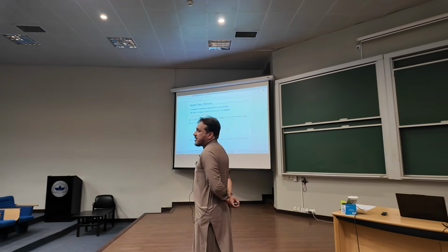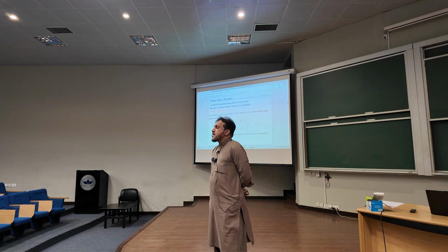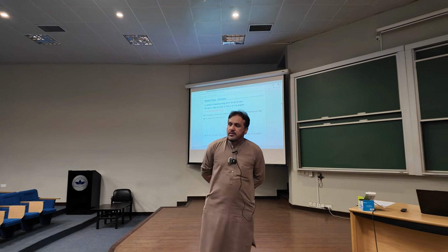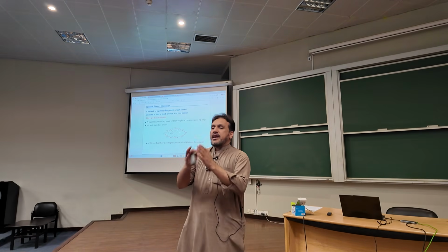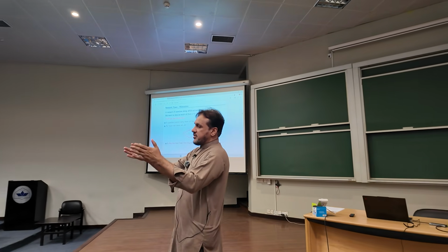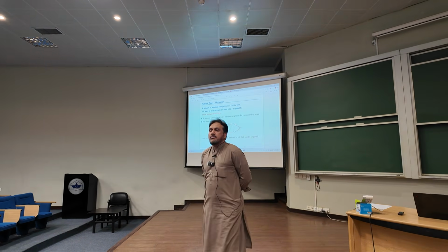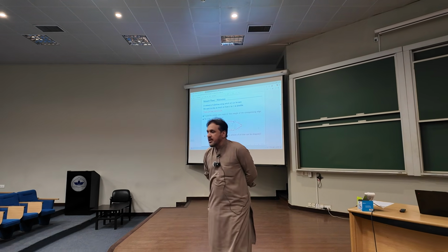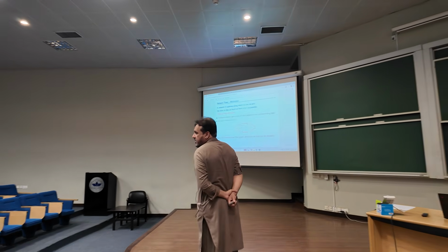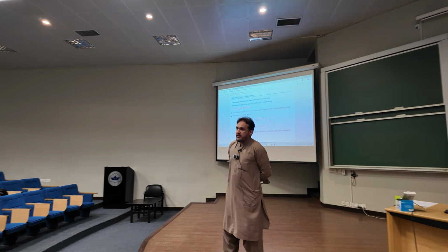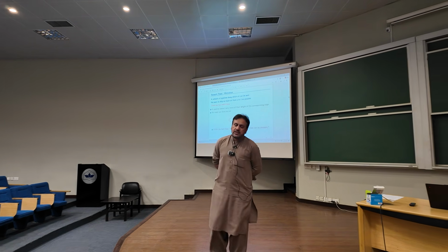The automatic meters, the AMI stuff, have the capability of negotiating with the power suppliers. The supplier can set up 10 units of flow from 3 to 4 p.m. Now it's your choice. You can use an air conditioner for the first 10 minutes and then it will be total load shedding, or you can have a light bulb and a fan going for the whole hour. So it's called a soft load shedding scheme.